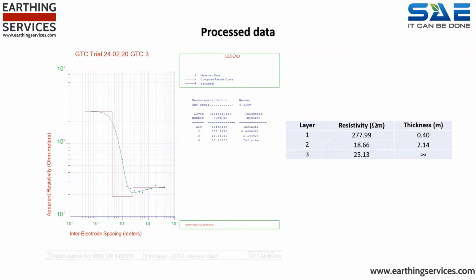Identified disparities on some of the test data were extracted from the data set, with the location 3 data verified to be accurate for the purposes of analysis. We use a suite of software when processing soil resistivity data called CDEGS, which is the industry standard earthing system software that is used globally, the accuracy of which is largely uncontested.